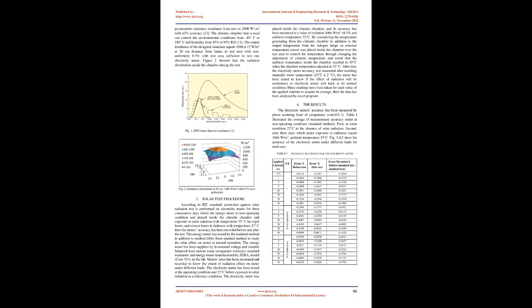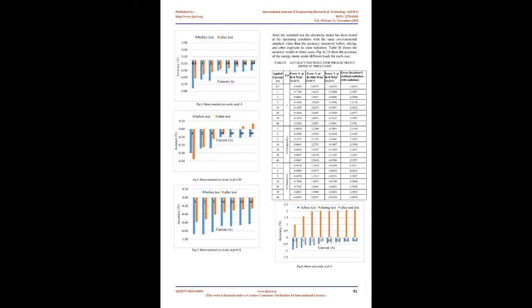2. Constructed solar simulator. In this paper, the solar test is carried out by using a solar simulator built by adding 4 units of quartz tungsten halogen lamps, QTH, with 250 W, 24 VDC each, on the climatic chamber model MKF 240. The lamps are supplied through 4 units of 24 V DC power supply manufactured by Meanwell, through wires coated with a thermal insulator to be protected from heat during the test.